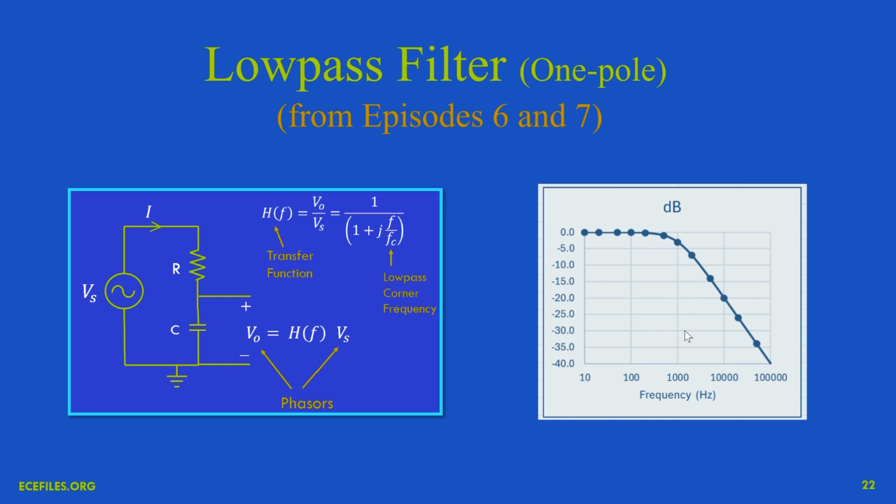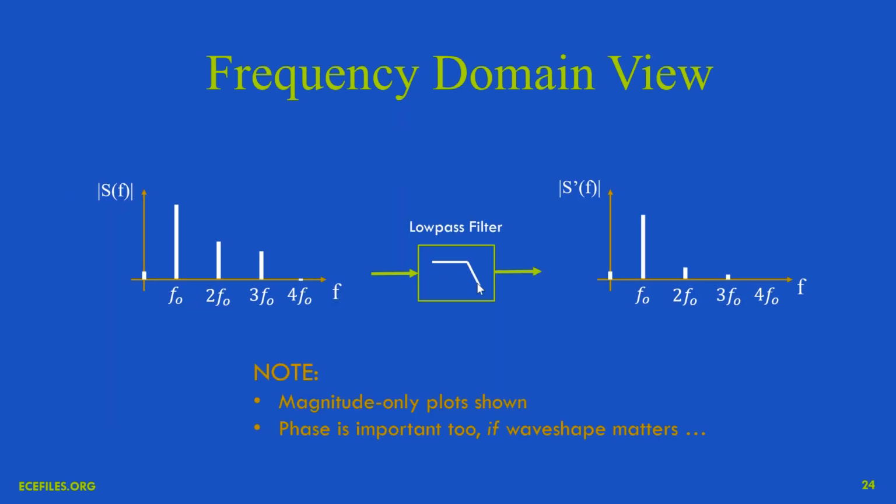The second harmonic would be out here at 2 kilohertz, and it's going to get reduced by 6 dB, and the third harmonic by even more, and so forth. And we can see the shape here in the box for a low-pass filter, echoing what we just looked at in detail there. So at the corner frequency here, we're down 3 dB, not very much, and you can see that this is maybe a little shorter than this one. That's what I tried to show. But the higher harmonics are out here in the so-called roll-off region, and the second harmonic, 2F0, is reduced by a significant amount, and 3F0 by even more.